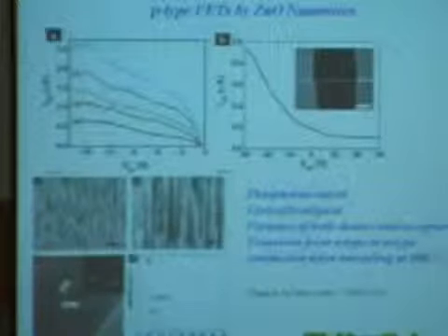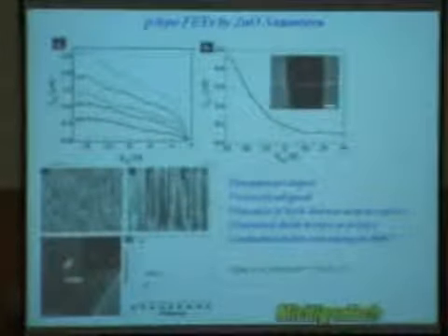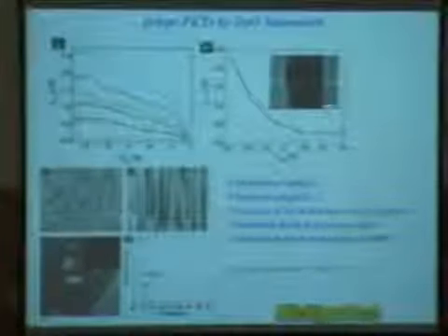And you can actually see that the devices demonstrated on zinc oxide always behave as N-type, because oxygen tends to have vacancies inside the zinc oxide. And it's very challenging to make P-type materials, and it was just published this year. So I'm giving you the latest information, right? It can be done with P-type single crystal materials, and it shows the gate effect of the P-type materials. However, this type of P-type zinc oxide is still not very stable at this moment.